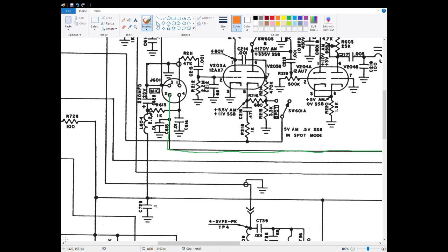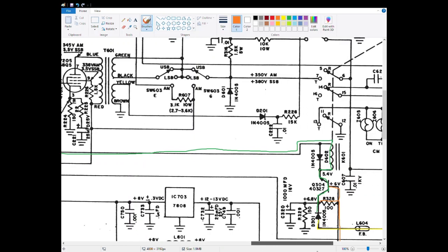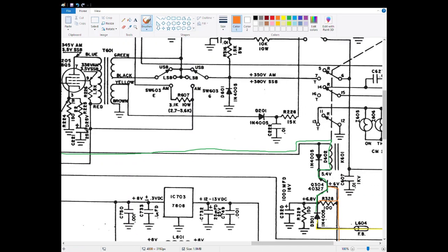Okay, pin number 2, I colored it green so you can see that's going to be the 6-volt wire or line from the relay. That's right where it says D602, and then you can see some indications for a coil and 2 lines. Feeds down into Q304, which is the transistor that, so I'll circle that right there, that guy there.